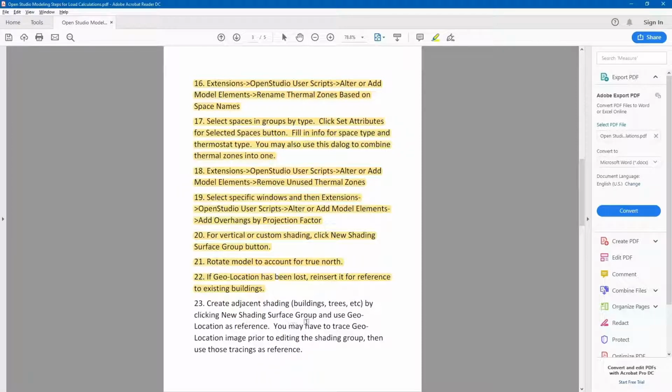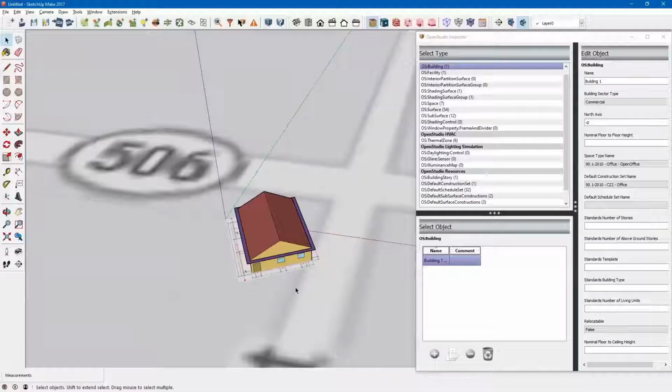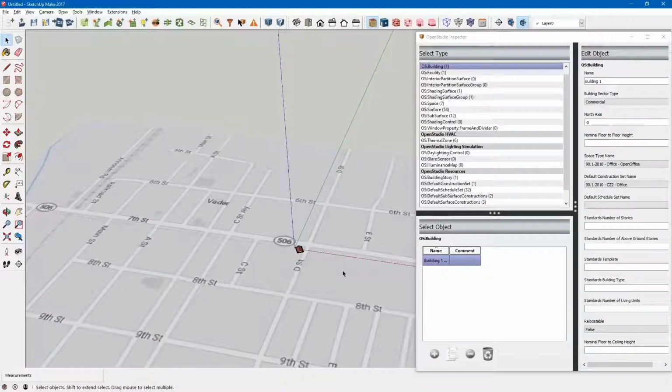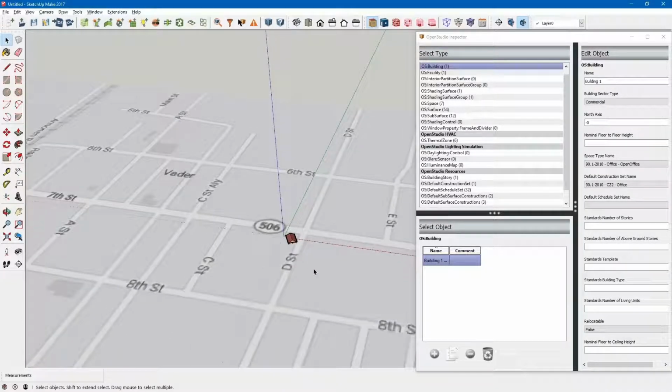And then at this point, you can create adjacent buildings, trees, etc. by clicking New Shading Surface Group, just like we did with the shades. And you can use the geolocation as a reference, and you can trace that location image prior to editing the shading group. This image is not...